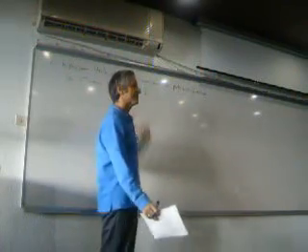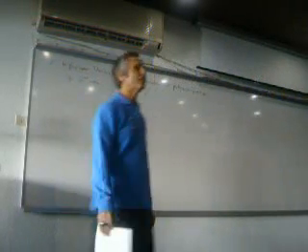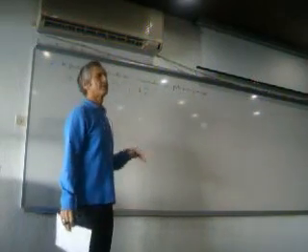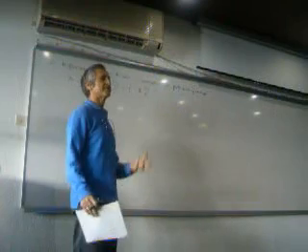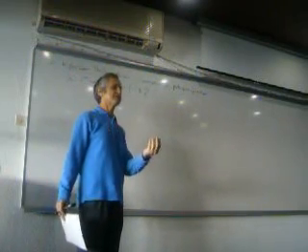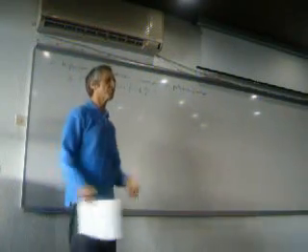No matter how stable the rest of the system is, if you force it with a growing function, the system cannot settle at the equilibrium point. The equilibrium point cannot be stable. You see? With a forcing function increasing over time, that's just obvious. So whether it's linear or nonlinear, the interesting, non-trivial part of stability analysis is done on the homogeneous portion.